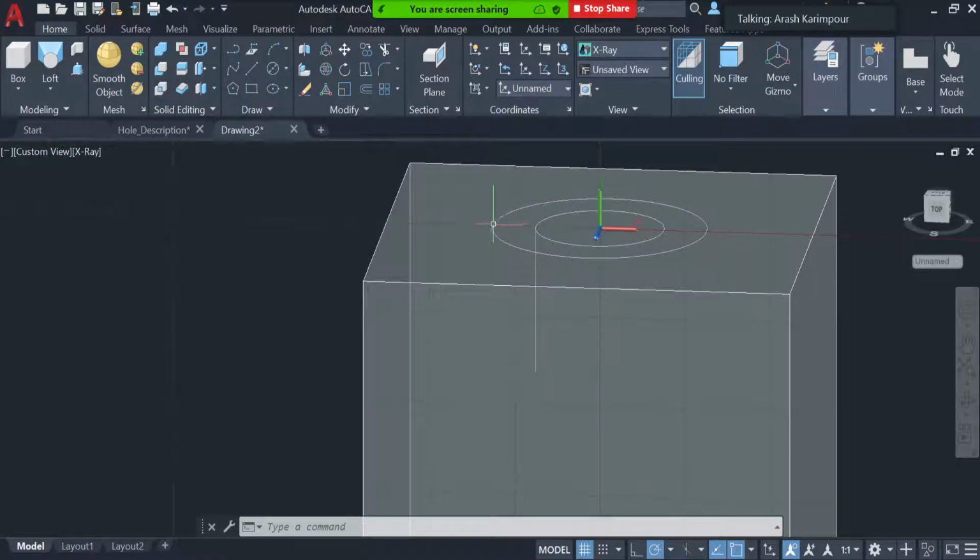Then I'm going to draw another line that starts from this point and goes at 45 degrees with respect to the horizontal line. That represents the slanted edge. So I click on the line, hold it on that center, move it to the left until I hit the perimeter of that cylinder, click on that, and this time I want it to be at 45 degrees.